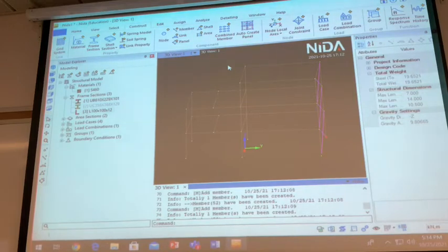Do you remember? According to the unit, you know this is 7 meters and then this is 8 meters. This is the U line. First, you can input the loading on each beam according to this pattern, but I think it's a bit tedious. Second approach is easy. I model a virtual slab, a panel element. The panel element can help to distribute the pressure to the beam by the computer program.